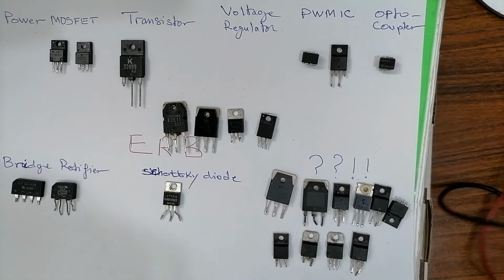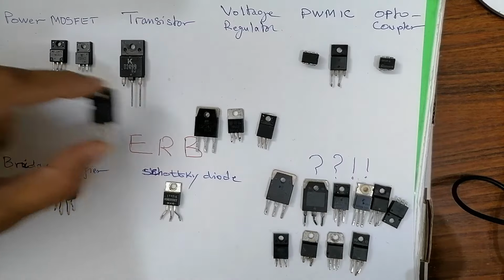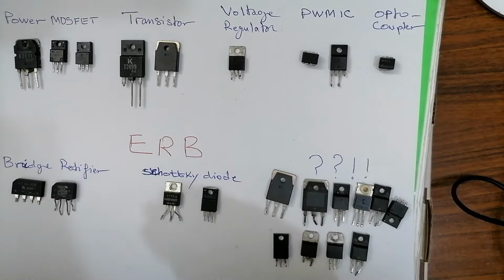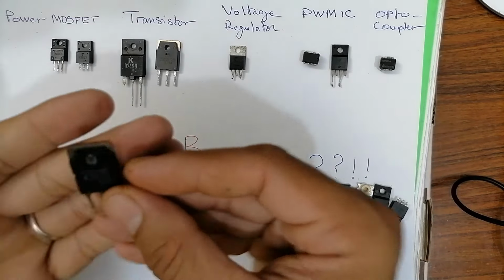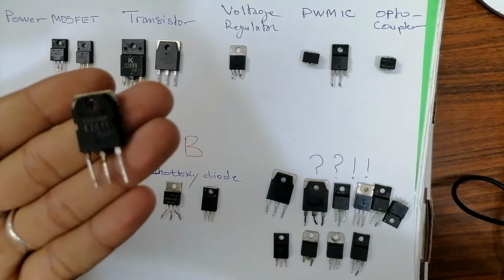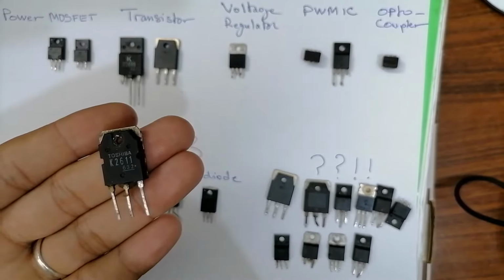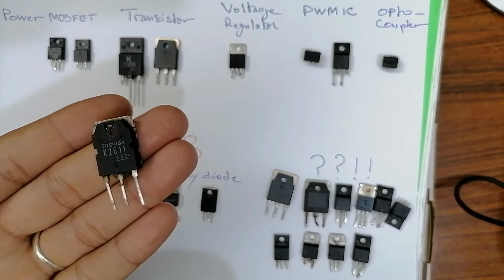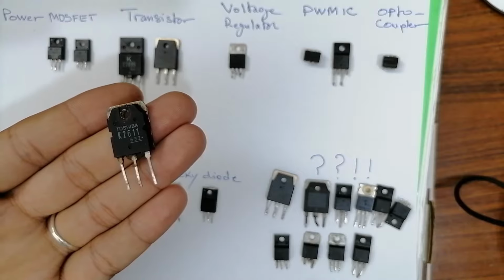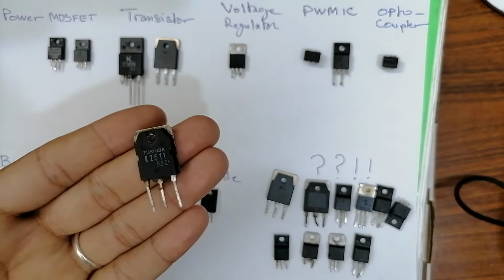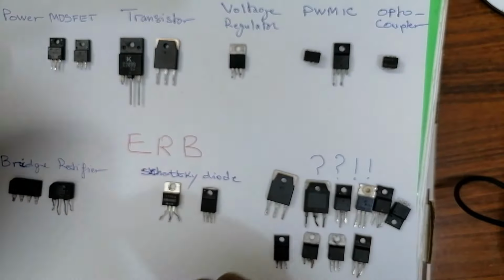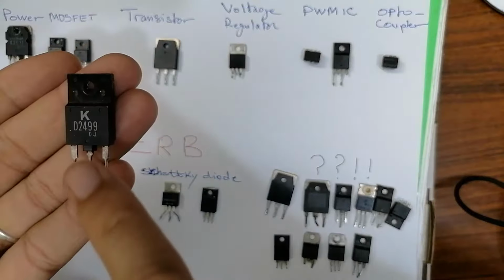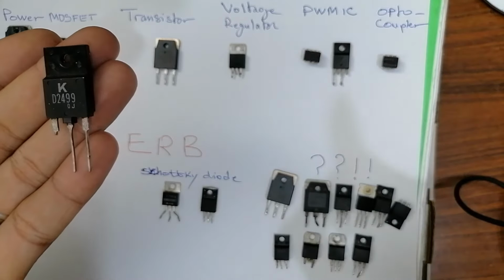Okay? So we can know about the type of component using basically 2 methods. By experience, for example, for me, when I see this number, as you can see over here, K2611, the component that begins with this number, for me, based on my experience, is always MOSFET. Okay? And others, for example, that begin with D24, as you can see, like this one, is transistor, not MOSFET.